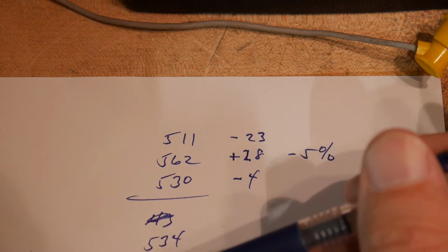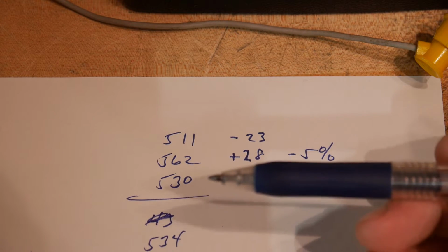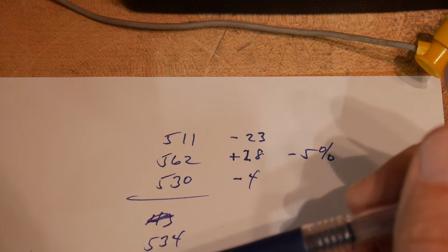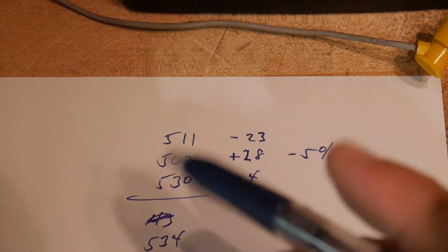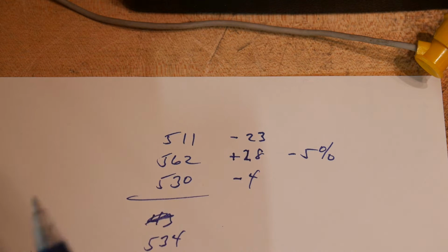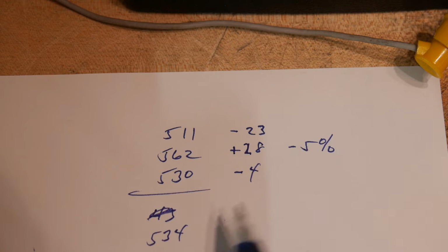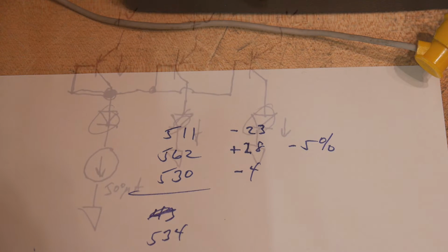There's other types of current mirrors. You can look up Wilson current mirror. It adds another transistor. It kind of adds it into a cascode place, I believe, and creates a little bit better voltage reference and tolerance, and doesn't vary as much. But yeah, we're looking at a pretty good current mirror. Very few components.